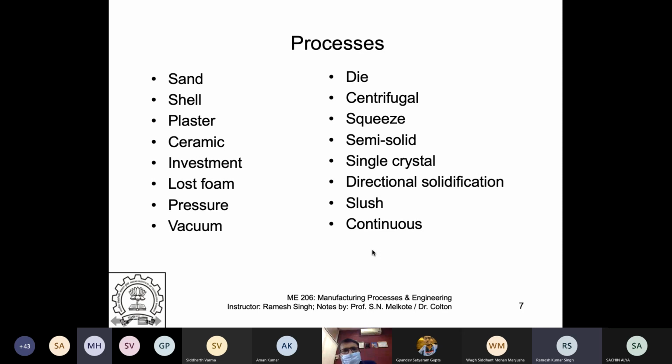Sir, no need of core for any hollow. Core is there. Everything is there. You make a shell out of that. So you mix the sand with the resin, and the resin cures. So instead of having the copes and drags, you get a complete shell of the sand and resin mix. You get me? So you get a shell, like a solid sand and resin.